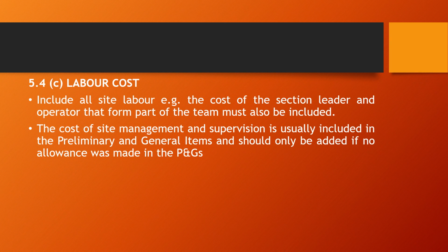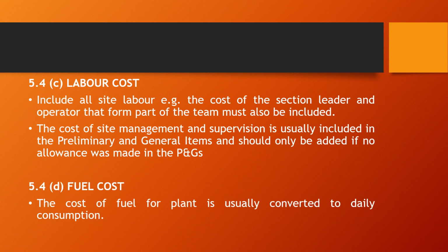The management, usually people like the health and safety officer, your site agents, your site engineers, those guys are usually paid under what you call the preliminary and general, also known as the P's and G's, so you wouldn't include them in the actual unit rates, unless the tender you are pricing does not have a P and G section. If they say include your P's and G's in the unit rate, then you would include it in the unit rate. But I'm going to show you next week how to do all of that.